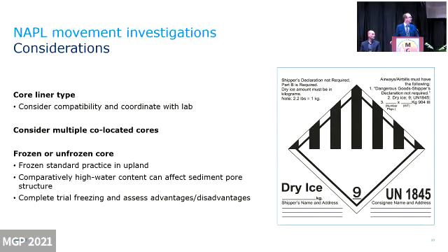And then lastly, on frozen versus unfrozen cores, the standard discusses this in pretty extensive length. In the upland settings, we're pretty accustomed to sending these types of samples to the laboratory on dry ice to lock in those pore fluids. However, in the sediment environment, we're typically dealing with sediments with pretty high water content, upwards of 60% or so. In that freezing process, that water also expands, and so that can degrade the core. And then when it shrinks back, when it is unfrozen, that can create some fractures in the sediment that can cause potential for NAPL mobility that might actually not exist in the actual native sediment.